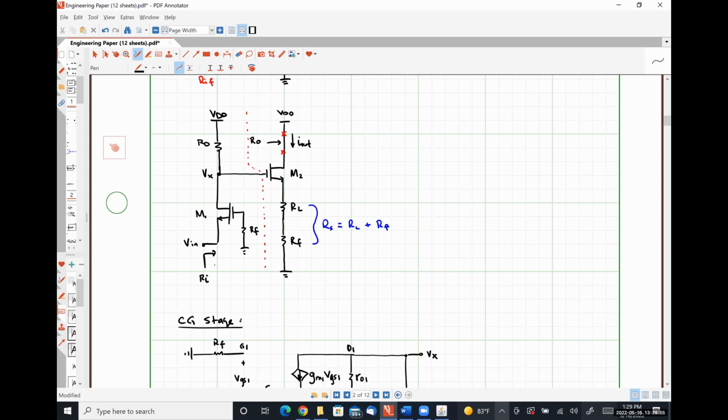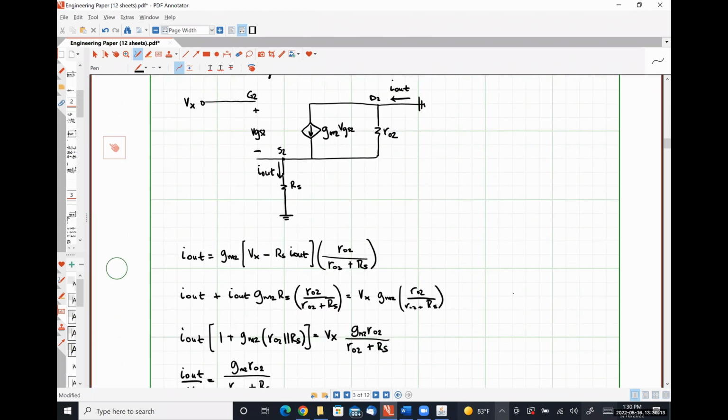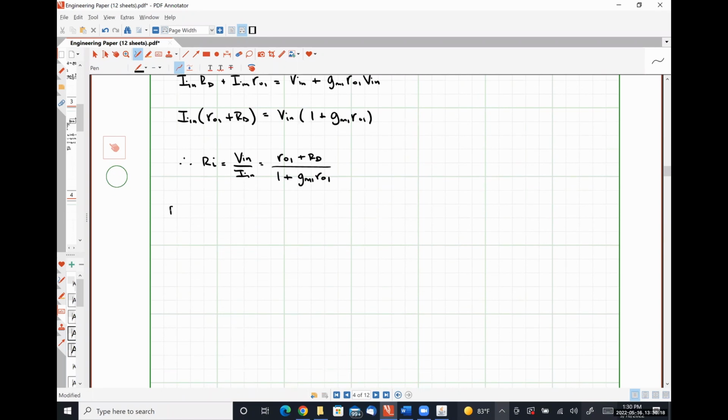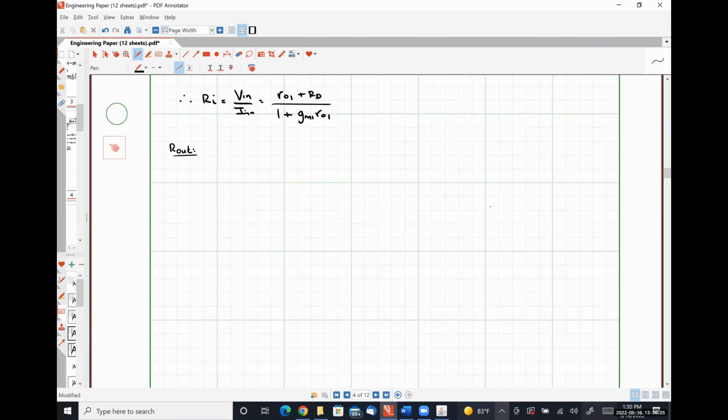So effectively, I'm looking at the output resistance of almost like a common source amplifier that has some sort of source degeneration. We can actually prove that pretty easily. Calculating R out. My gate terminal is grounded.